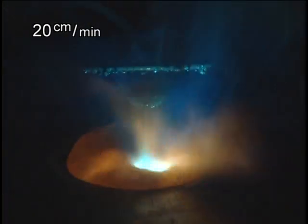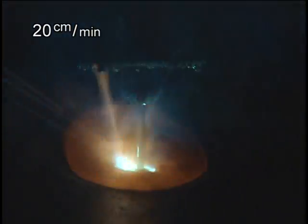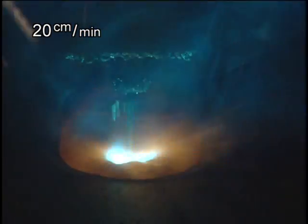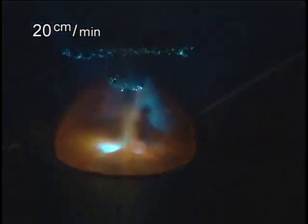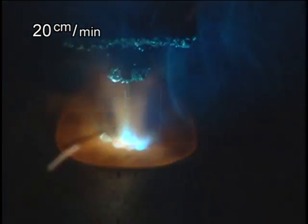This is an arc condition created at 300 amps, 30 volts, and a travel speed of 20 centimeters per minute. When the travel speed is too low, the weld pool is widened and the molten weld metal flows around and ahead of the arc to hamper the stability of the weld. This is noted by the unstable sound of the arc.